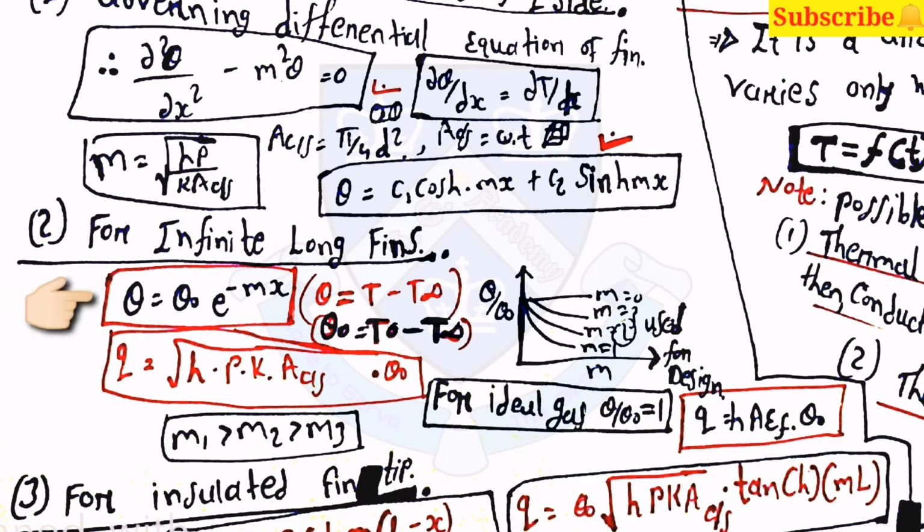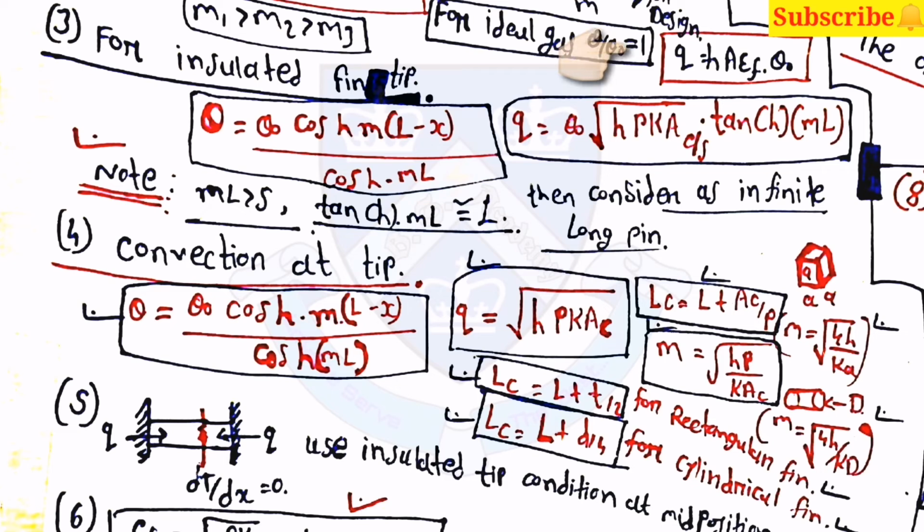Here theta is equal to T minus T infinity, and Q is equal to the square root of h into P into k into cross-section area, into theta naught. Then here m1 is greater than m2 greater than m3, and for the ideal case theta by theta naught is equal to 1, and Q is equal to hA into epsilon f into theta naught.